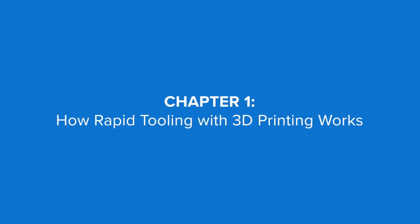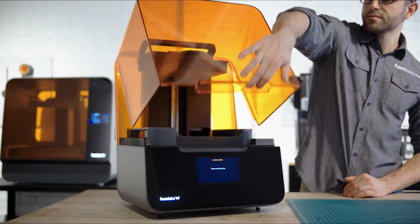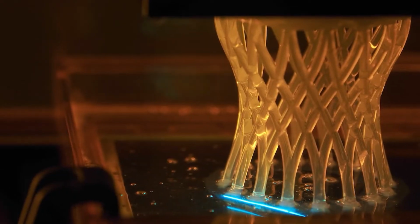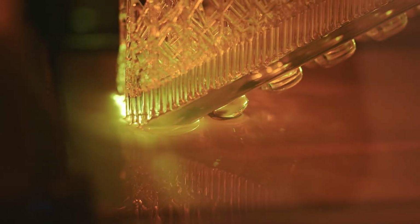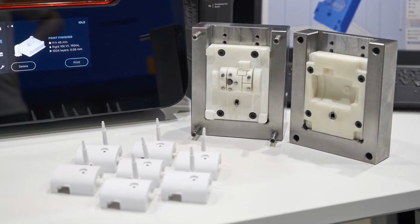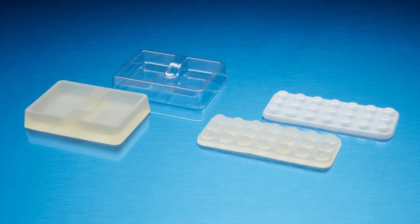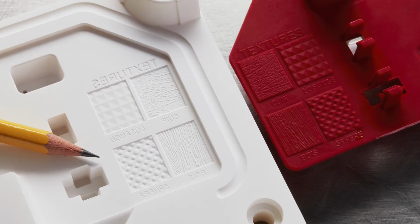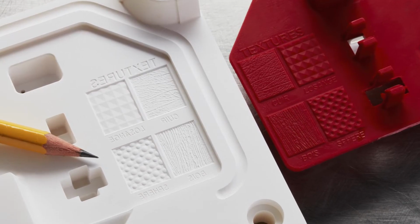How rapid tooling with 3D printing works. Stereolithography, or SLA 3D printing technology, is a great choice for quickly and cost-effectively producing 3D printed rapid tooling. Molds, patterns, or dies produced with SLA 3D printers are accurate and have a smooth surface finish, which will be transferred to the final part with high precision.